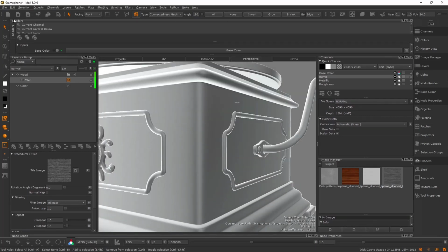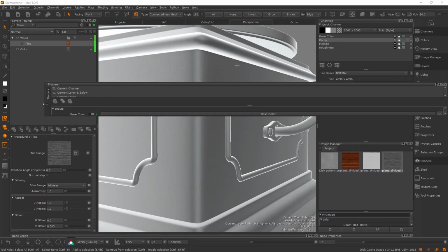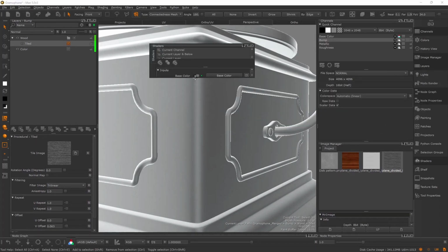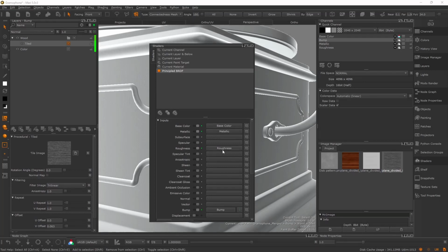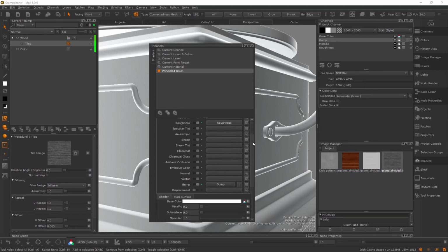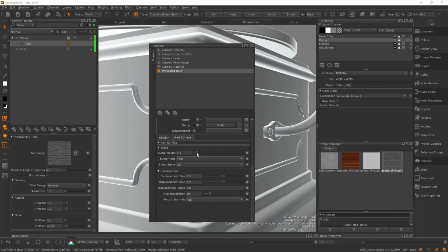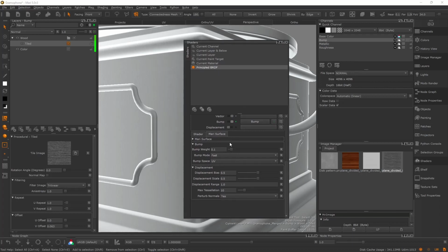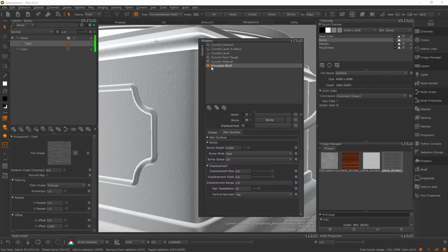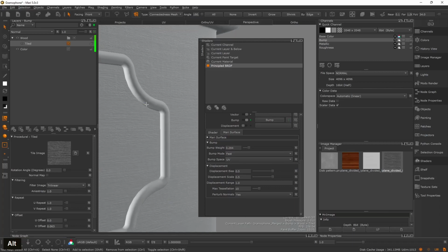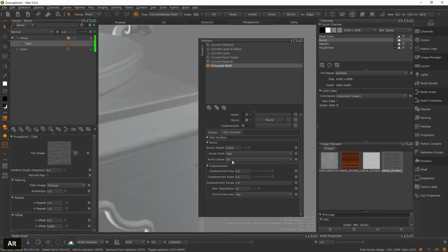As you can see inside, all right, as you can see here, we have base color, metallic, roughness and bump. Down here we have control over the bump weight. So add more bump to the surface. We move that like so. All right, now as you can see, we have some bump going on here. I'm gonna leave that on 0.4 for now. All right, close that up.